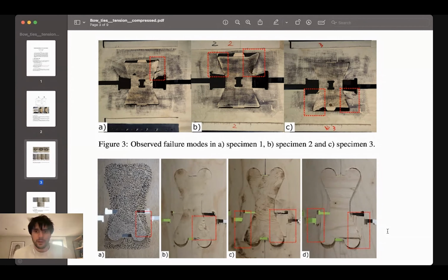Right. So the place I would like to start to talk about the performance of WikiHouse walls is starting with the bow ties. So as we talked through in the previous part of the video, we did recognize that the bow ties are the elements connecting the columns together. So they act as shear keys, and you also connect the columns to the end beam or the normal beams. So they act as hold downs.